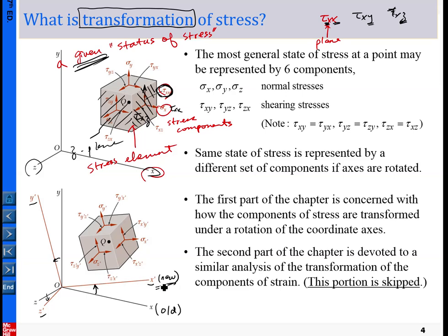And the new coordinate system is in a certain transformation relation to the old one. That is where this transformation comes from. That transformation is regarding the transformation between two different coordinate systems, and each of the coordinate systems can be used to describe the stress element. So basically we simply want to describe the transformation of the stress, which is to say you are asked to calculate or determine each of the stress components in each coordinate system, depending on which one you are specifically asked for.